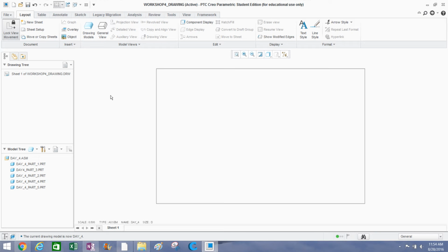Alright, so you have all 5 drawing models imported to the sketch. What we're going to do is go ahead and create our first view. We'll warn you, Pro E has some really weird ways of setting up the views, so we might have to go back and change some of the views so that they show the way we want them to. We'll go through that as we need. Since we have the assembly toggled in the model tree, we're going to be dealing with any kind of assembly view. So it's going to show everything together.